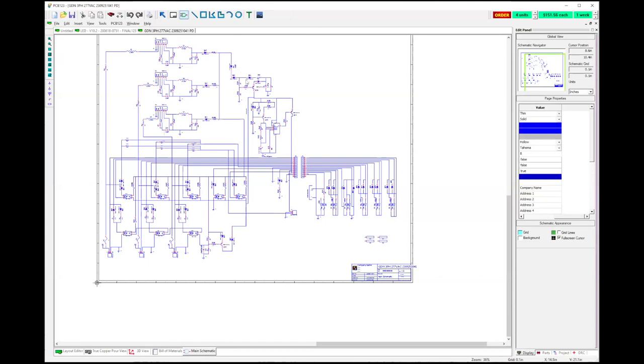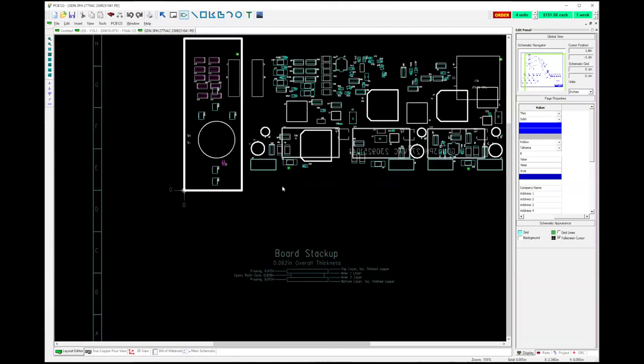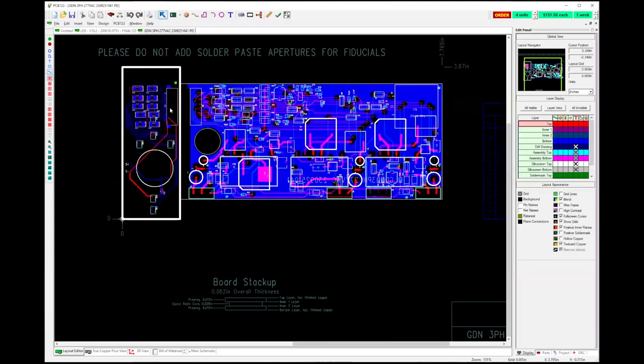And I try and do my schematics sort of along the lines of how the circuit board's going to be laid out, so I can have some correlation to that. You can't do it exactly, but it makes a lot more sense that way. And then again, you can modify your board to fit the necessary physical parameters. This is 2 circuit boards that plug together with a ribbon cable. So I put a slot here so I can just clip the 2 boards apart and off we go. And this red feature is a slot. This is a cutout; it fits over a boss on a part.